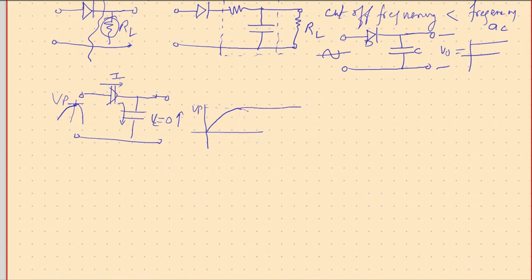So, what would have happened if the capacitor was not there? Then the output would have gone low. Then again, in the second cycle it would have continued this way, whereas because of this capacitor the output remains constant. So that's the concept of a filter.